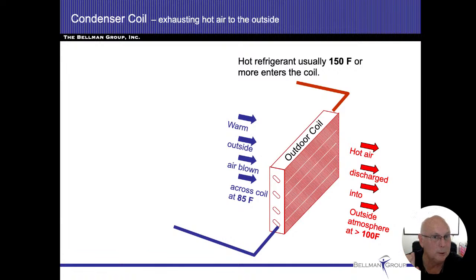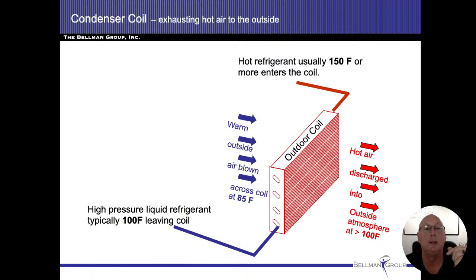And that's a real simple, easy test that we could do to see if these things are basically doing what they're supposed to be doing. We turn the air conditioning on. If it's 70 degrees in the house, we should be expecting it to be 50 to 55 degrees on the other side of the air conditioning coil in the plenum. Anything that's higher than that or lower than that could be an issue.